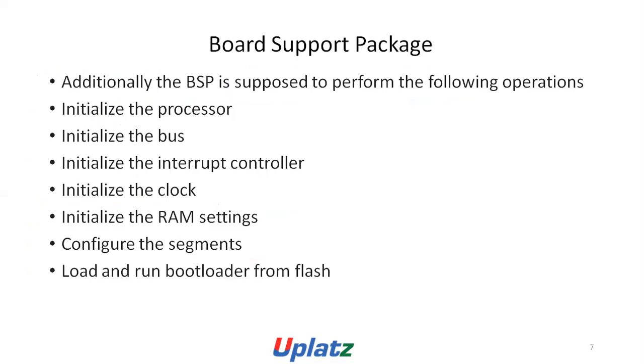Board support packages. Additionally, the board support package is supposed to perform the following operations: initialize the processor, initialize the bus, initialize the interrupt controller, initialize the clock, initialize the RAM settings, configure the segments, and load and run the bootloader from flash.